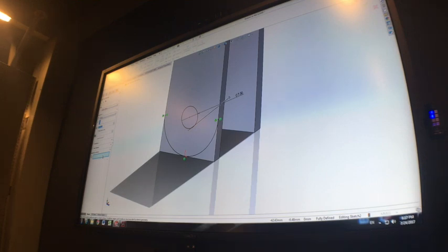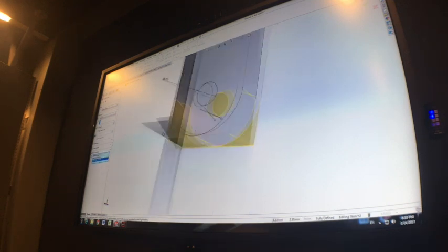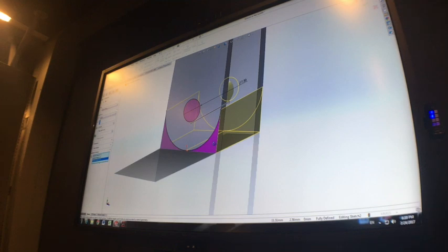Because we did this sketch on the face, it's also going to use the edges of that face to bound our different contours. Okay, so I'm able to select that hole on the inside and then these two bottom corners as segments that I'm going to cut.